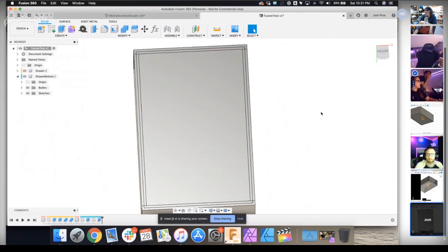Is there a way to go in and edit it if you mess it up? Yeah. Whenever you hit enter, it'll give you the little dimension bars where it says fx. You double click on that. Okay? So drawer depth minus dado, tab, drawer width minus. I hit minus dado and then it deletes the drawer width. So drawer width minus dado minus dado.